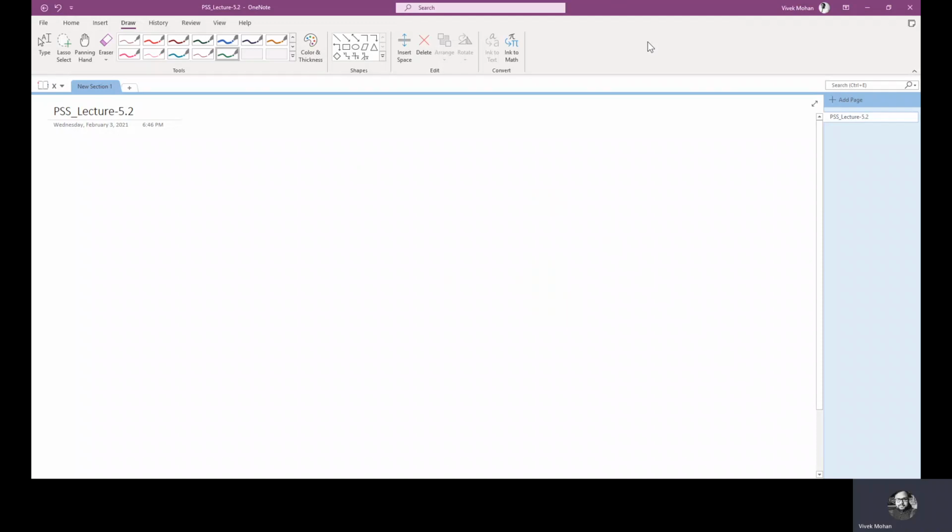Okay, in this lecture, we are going to study the active and reactive power flow in power systems. We already have the expression for active power output of a synchronous machine, which is P equals EV by XS sin del.